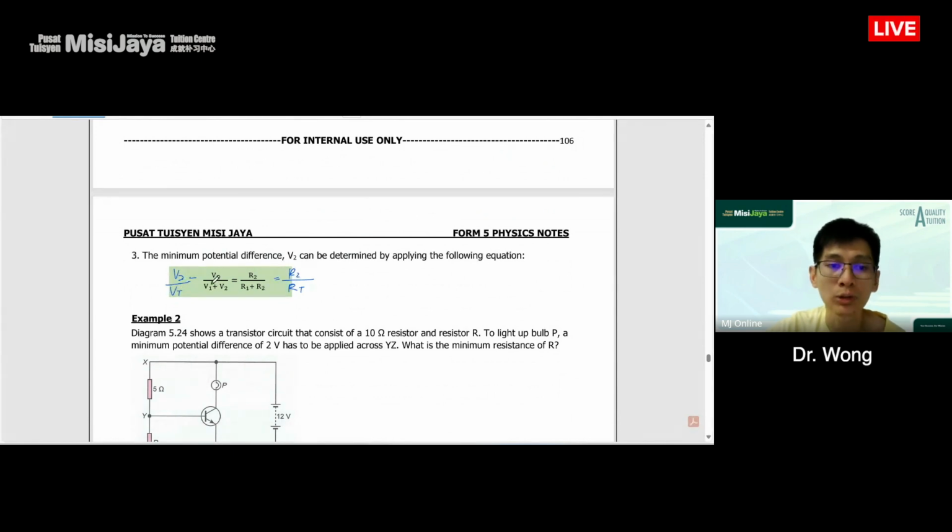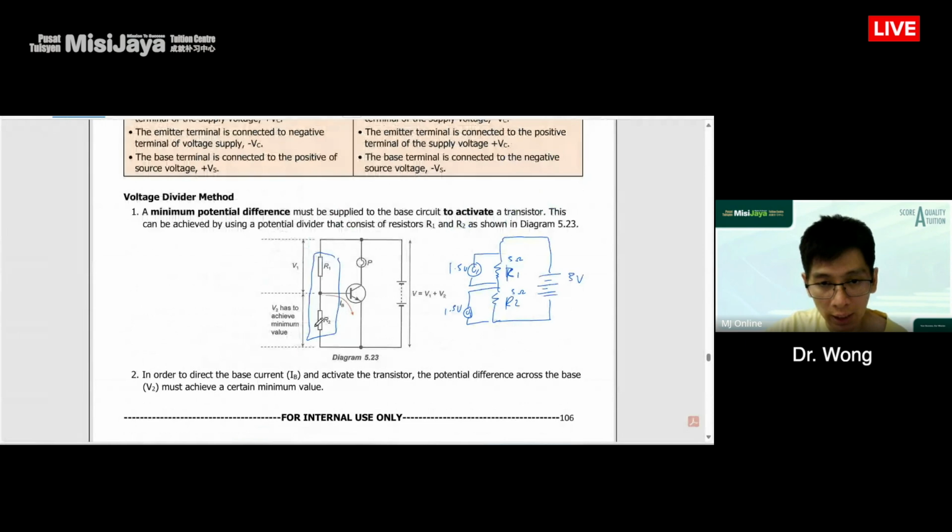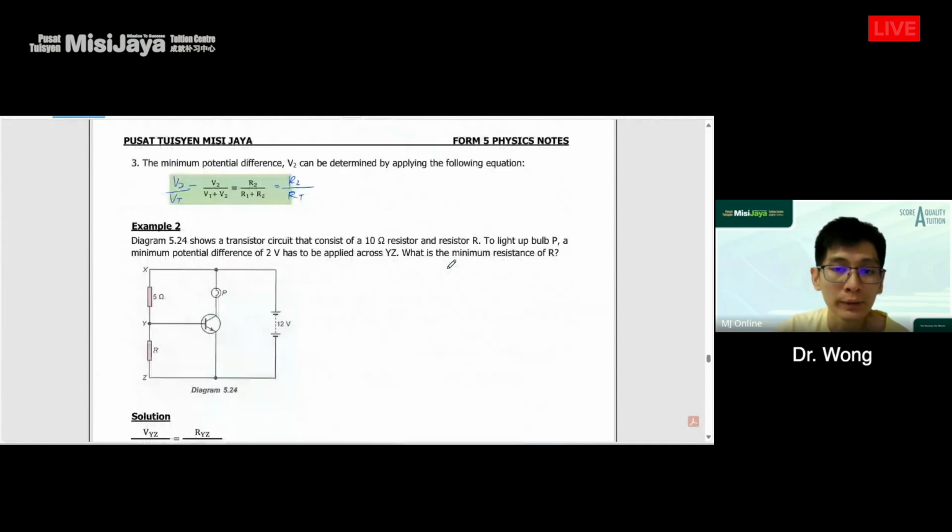Total voltage also equals V1 plus V2, because in a series circuit V1 plus V2 equals V total. In parallel, from the top until the bottom, the components share the same voltage. If it is 3 volts from the top, and I have another voltmeter, number 3, going to the bottom, we will also get 3 volts. Okay, so let's move forward.